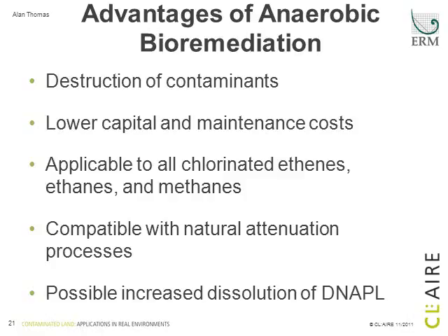I just wanted to add a little bit more about the advantages of anaerobic bioremediation, because I think it is an emerging technology and maybe a little bit less understood than the traditional aerobic biodegradation. The key thing, as I've mentioned, is that it's focused predominantly on chlorinated solvents. It results in destruction of contaminants. It may have lower capital and maintenance costs than some of the other more traditional technologies. It's applicable to all chlorinated ethenes and methanes, and it is compatible with natural attenuation processes as well.